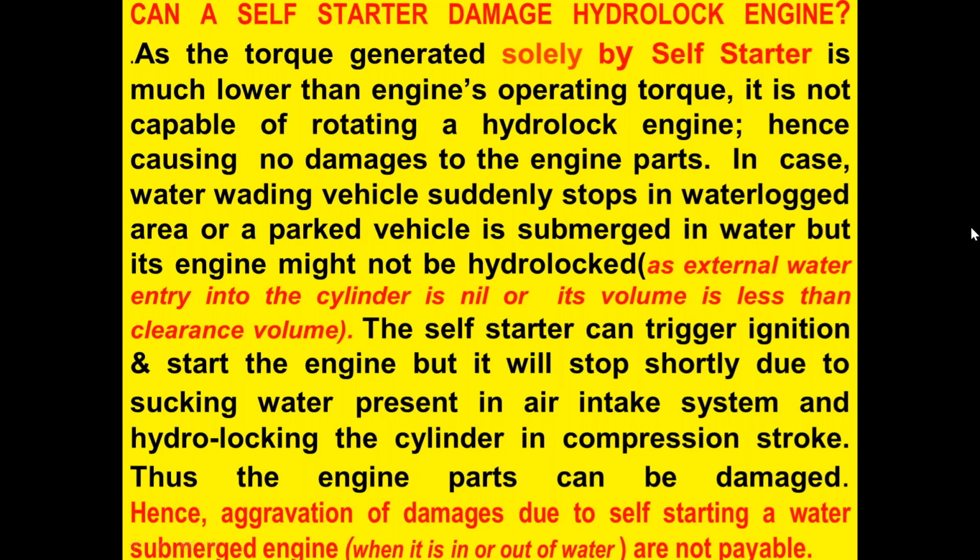But there is another different case. A water wading vehicle suddenly stops in a waterlogged area, or a parked vehicle is submerged in water, but its engine might not be hydrolocked, as external water entry into the cylinder is nil, or its volume is less than the clearance volume.